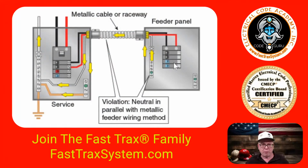Some people say, well, Paul, just remove this screw. And now this bus is isolated. Well, first of all, we don't know that it's isolated, because it could be screwed straight to the metal enclosure, even though they did put the green screw in there. So it needs to be floating, not in contact with the metal, okay? And you see this bus over here, which does have the green screw. This is fine because that connects this bus to this enclosure.